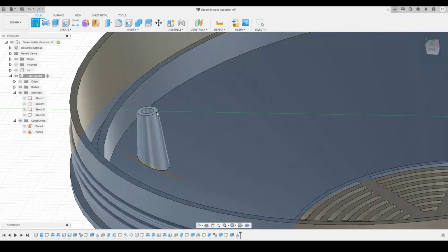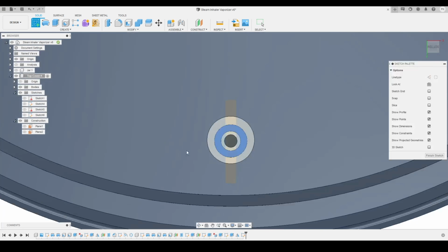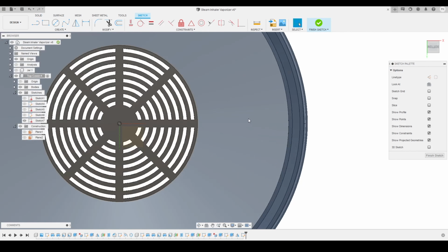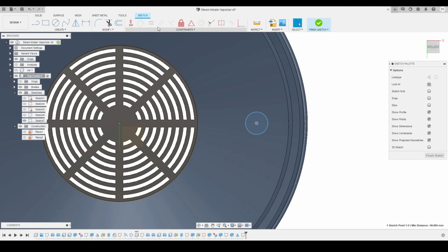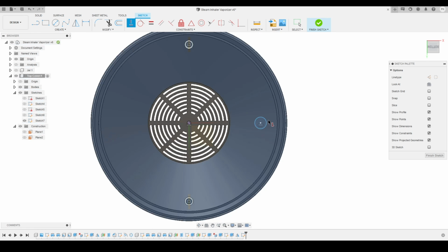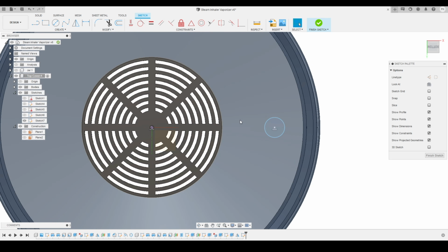I will activate the create sketch tool. We'll select the top of this feature as a sketch plane. Here you can see my tools are active now. My sketch planes are also active now. So now I'm going to create a circle over here like this. I will make sure that these two points are on the same horizontal position. I applied the constraint between these two origins, and here you can see this is the circle that we had created.